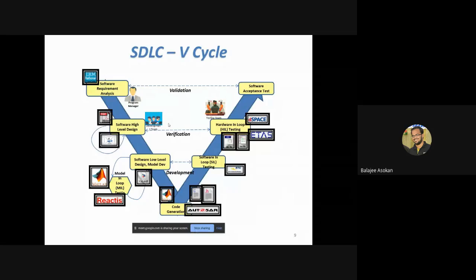Once all of this is done, they will do the testing and validation at this stage to see whether the given signals are responding and behaving properly. So far in our simulation, all the sensor inputs we give manually, and the actuator outputs we see using a scope block. This was done at the MIL and SIL stage.